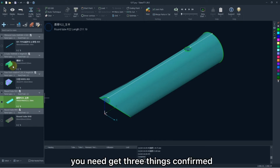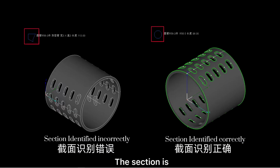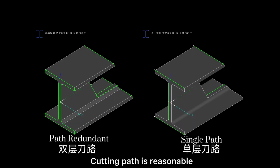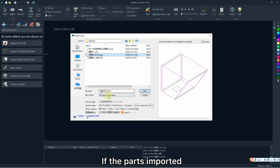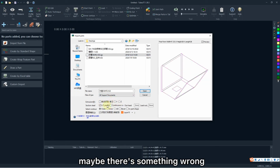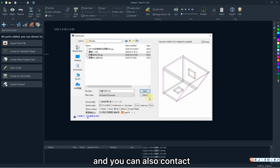You can browse the parts respectively to check if they are imported correctly. To ensure that, you need to get 3 things covered. The section is identified correctly. Extrusion direction is along the y-axis. Cutting path is reasonable. Generally, you need to check if there's no redundant cutting path. If the part imported cannot meet the requirements above, maybe there's something wrong in the import interface. More details on it we will talk about in the near future, and you can also contact us by email